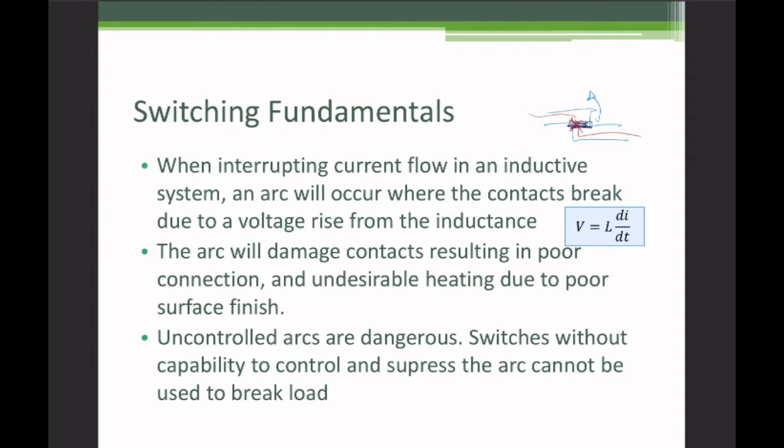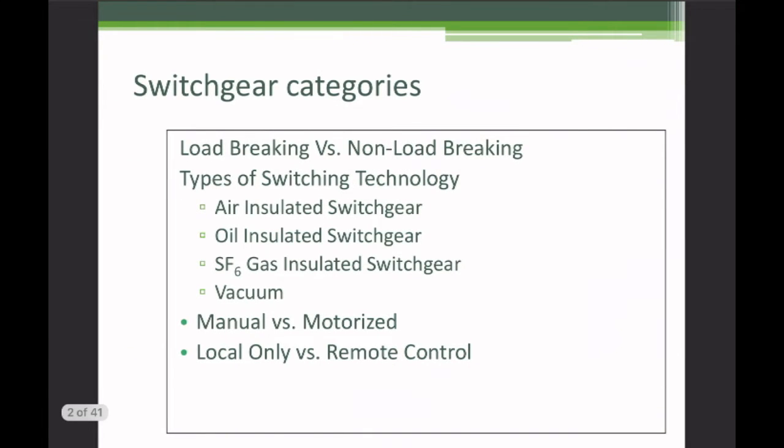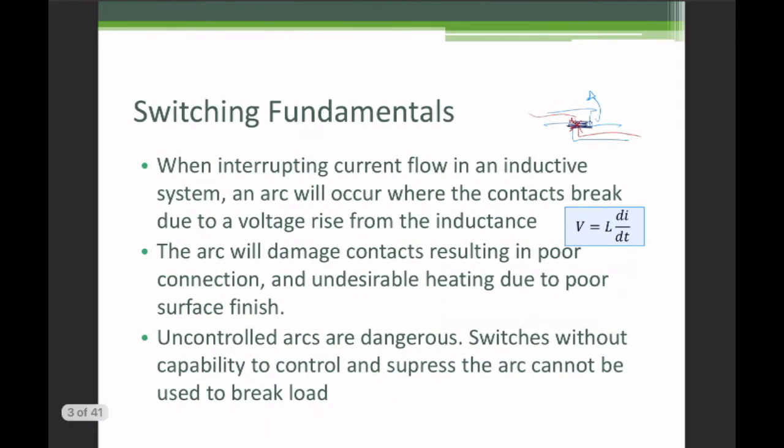So for our first category, load breaking versus non-load breaking, we now have our answer. A load breaking switch has the ability to control and suppress the arc that occurs when you open it with current flowing, whereas a non-load breaking switch does not have that capability.